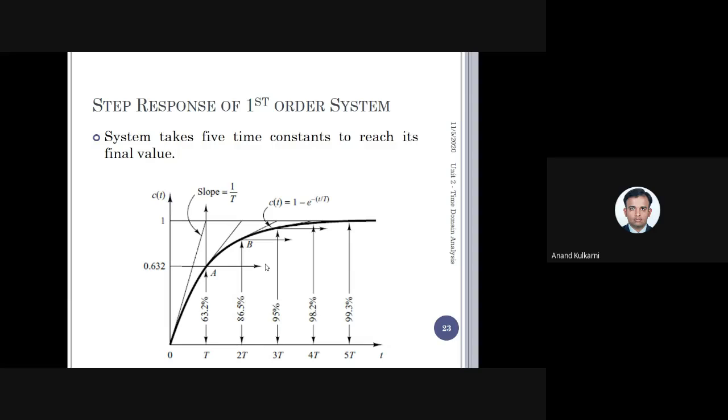If the temperature is rapidly changing, you have to use a device whose time constant is small. Whereas if the parameter to be measured is steady, whichever you use, it doesn't matter. So for example, if you are taking body temperature or water temperature, in that case you can afford a sluggish device like a mercury in glass or alcohol in glass thermometer, because here time is not important for you and the temperature of that water is constant.